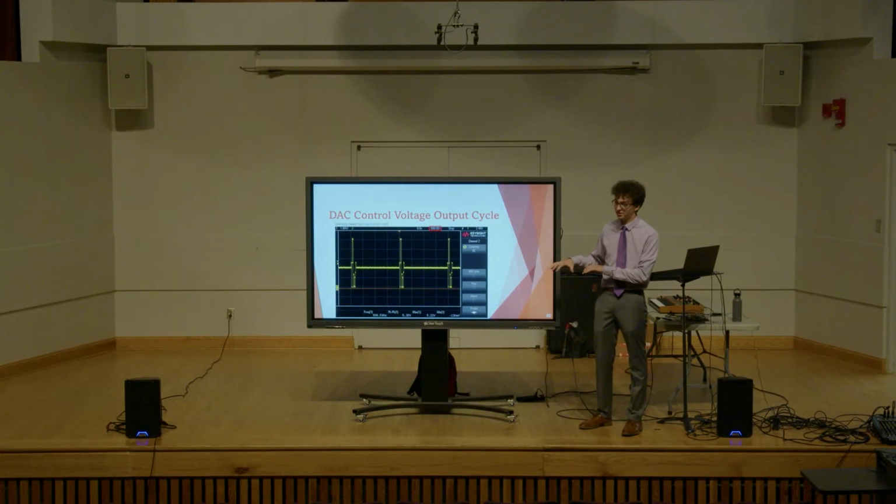But on top of this, this is just one DAC output, which is feeding all of the multiplexers. So it has to feed all the individual control voltages in series. But if I decide to split them up along all 8 of my available DAC outputs, I could have the number of control voltages divided by 8 running out of these 8 all the time. So I've effectively cut my cycle time down, or divided my cycle count time by 8.